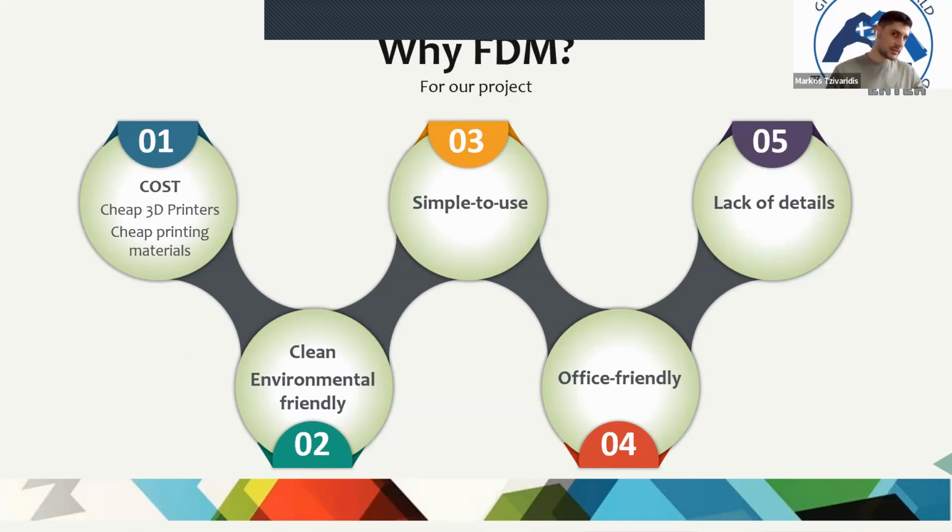Today, this has changed a little bit, which means that instead of 100 euros, you can find resin that costs 50 euros, for example. But still, it's more costly than FDM printing. But I wouldn't say that you cannot use SLA printing as a home printing method. The only problem here is that when you use SLA, it is a little bit toxic, and you have to take some measures in order to not hurt your health.